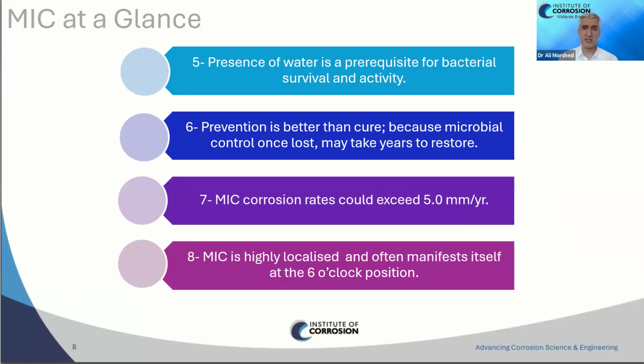Presence of water is a prerequisite for bacterial survival and activity. It's a very important point. No water, no MIC. Prevention is better than cure because microbial control, once lost, may take years to restore. This is something we have to remember when we commission a new asset. It's worth maintaining a corrosion control system in such a way that bacteria and MIC are not introduced, because once they enter the system, it will be extremely difficult, if at all, that we can get rid of them.